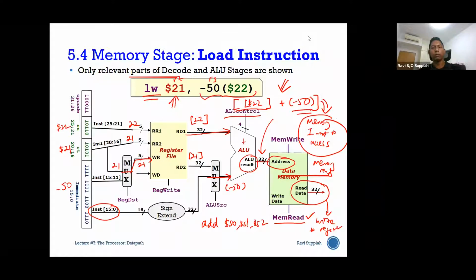So the idea is we already have a register file, ALU, and memory, and we want to reuse the same main blocks to fulfill all the different types of instructions. We need to be able to make decisions on how data is going to move from one stage to another, and that is where all these multiplexers and control signals come in.